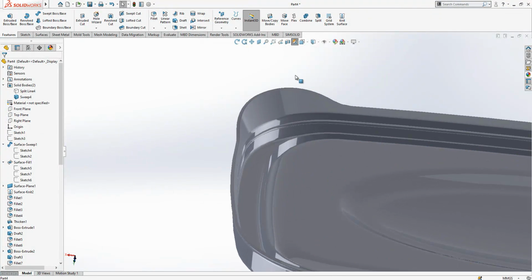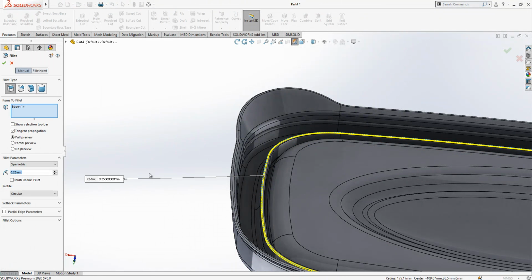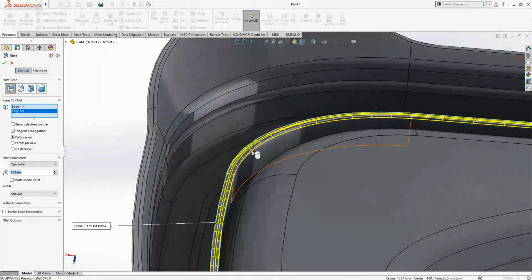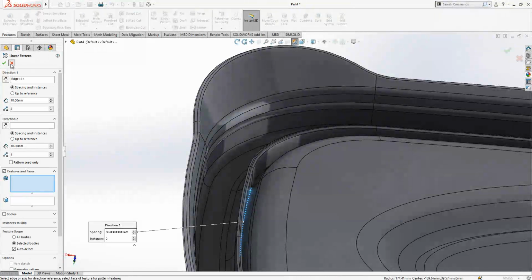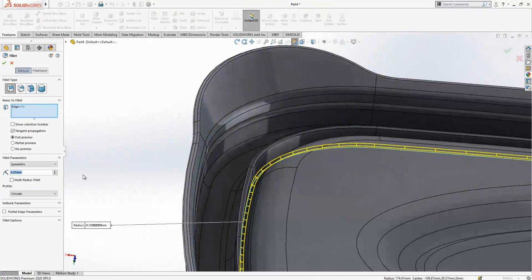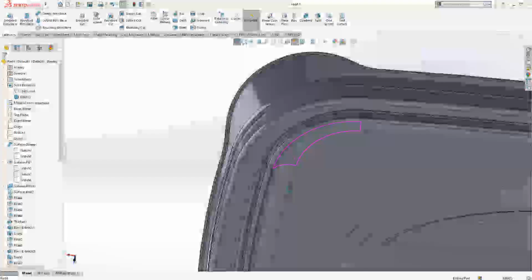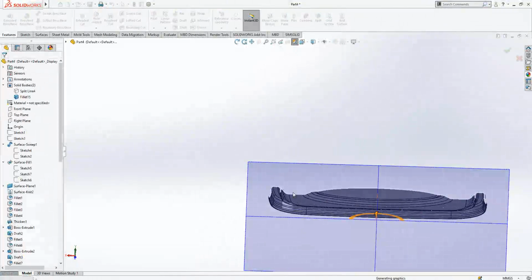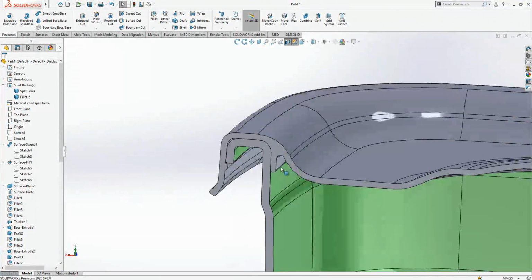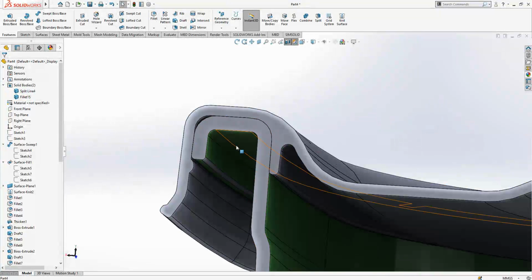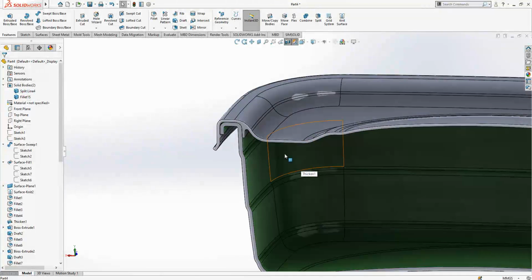Yes, we have an edge here. That's a thing to create an extra tension between the cap and your body, container body, and it is important to provide that. Also, it will help you for centering. 0.5. I added some radiuses here, and if you look the section now, you will see something like this. Yeah, I'm pretty much done. Don't forget, there should be a gap in between always in the plastic parts, and if not, it is difficult.